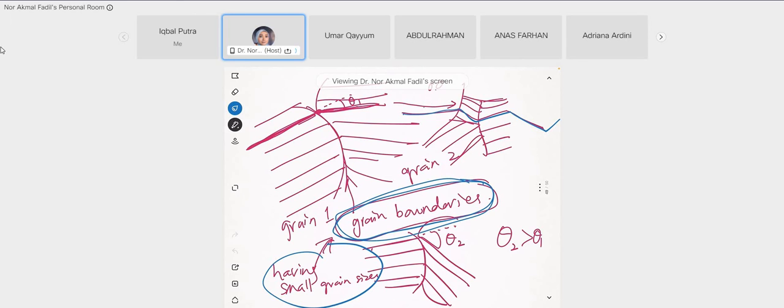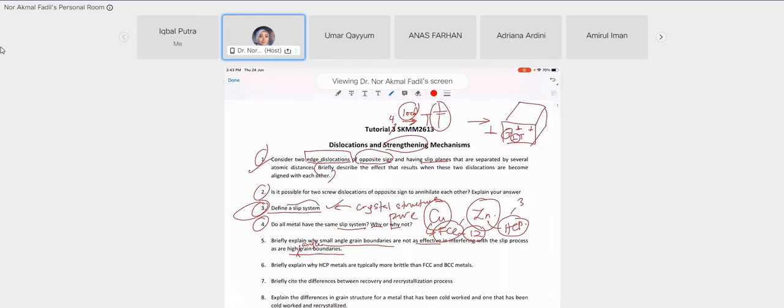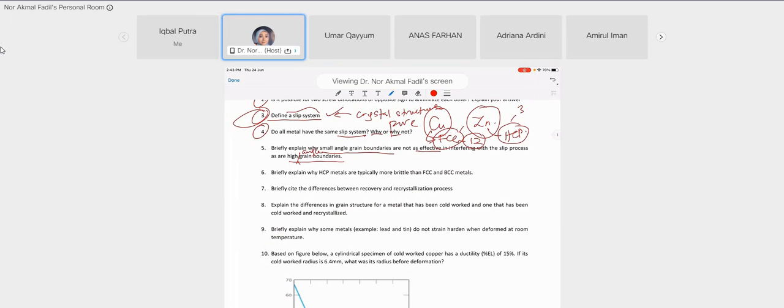If strain hardening is not applicable, maybe straight away change the materials. Find some new materials with specific alloying elements so you can increase the strength through the solid solution strengthening mechanism.